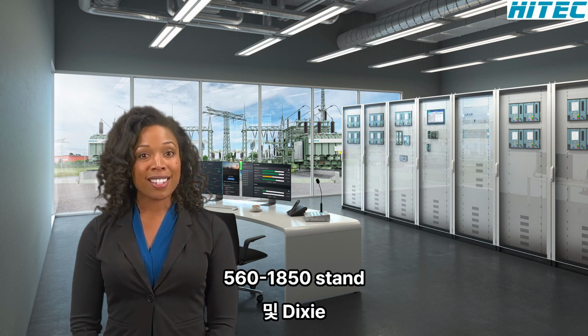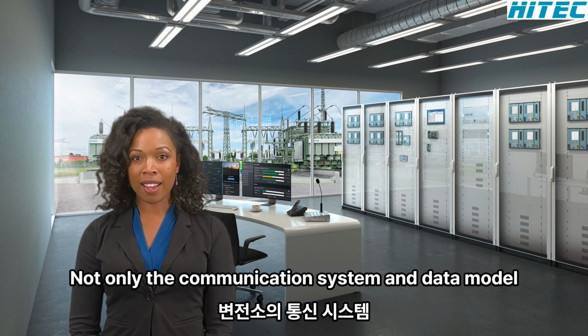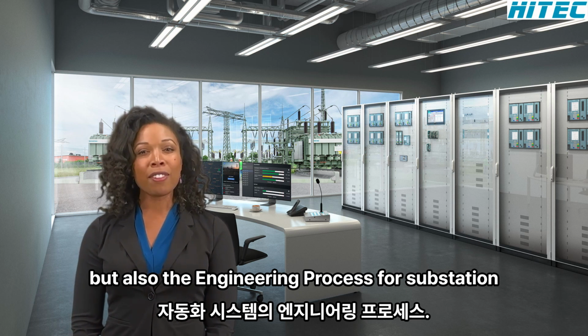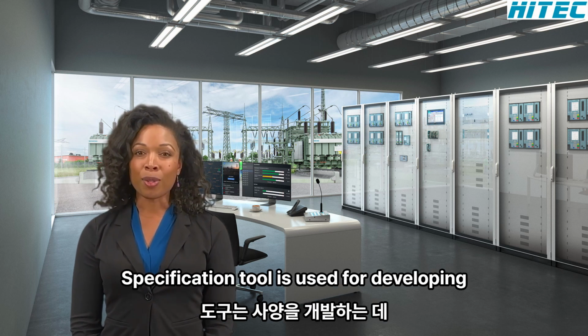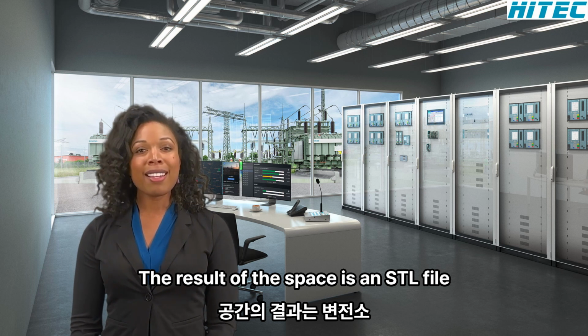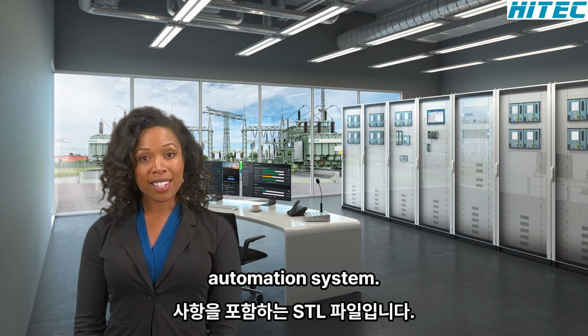The IEC 61850 standard defines not only the communication system and data model in the substation, but also the engineering process for substation automation systems. In the first phase, the so-called system specification tool is used for developing the specification. The result of this phase is a SCL file containing the requirements of the substation automation system.